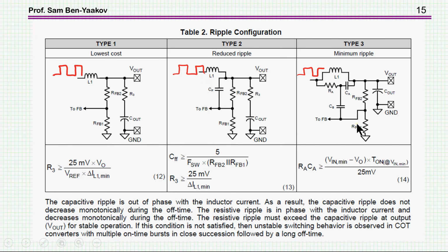Or, which is probably the best way to go, is to have just about no ripple here, but to add an artificial ripple, you might say, by tapping the midpoint here, or the switching point, and through this getting ripple, which is fed to the feedback, to the controller, to the comparator, but at the output you have a large capacitor. There is almost or practically no ripple. This is probably the best way to go, and it's fairly simple.